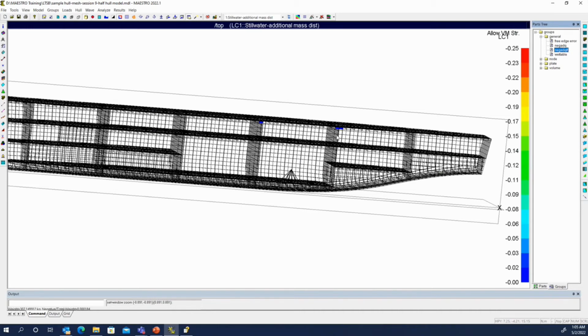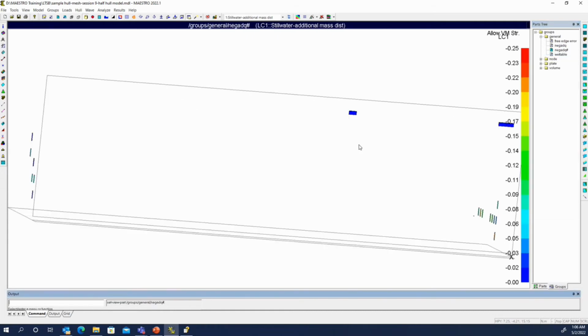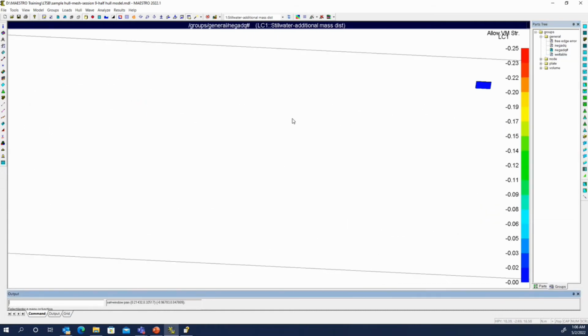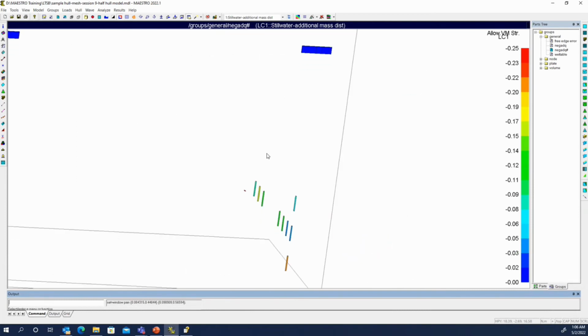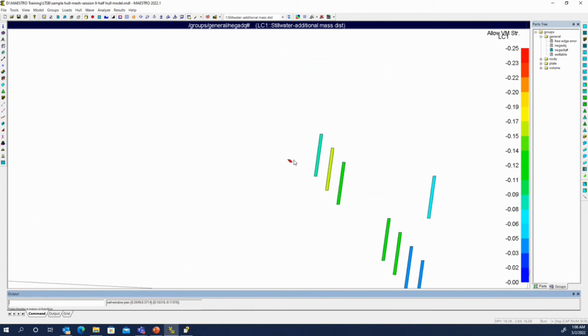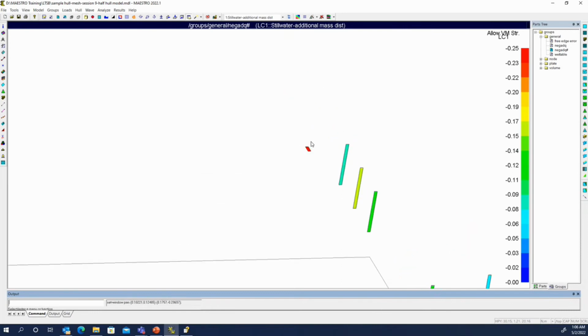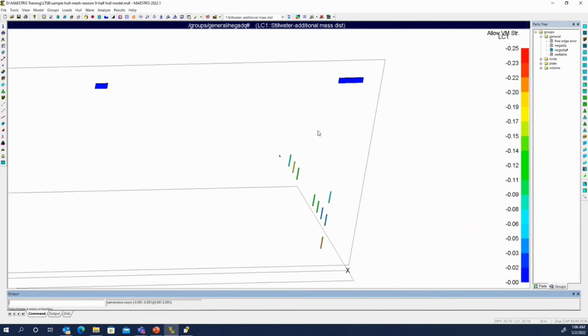If you wanted to extract each one of these, as you extract each one, you can simply click on it again or hit F2 or right click and say rename and change the name to something descriptive of which criteria was being evaluated there. But we make that our view part. Now it's much easier to look over everything, and there is the culprit. It was a very small horizontal beam at the end of the bulkhead there.